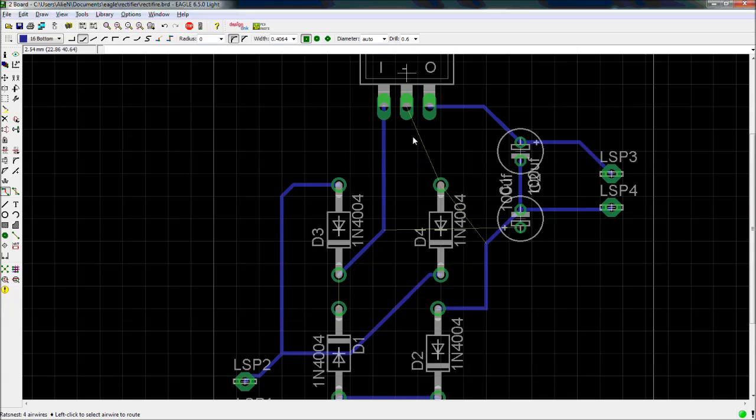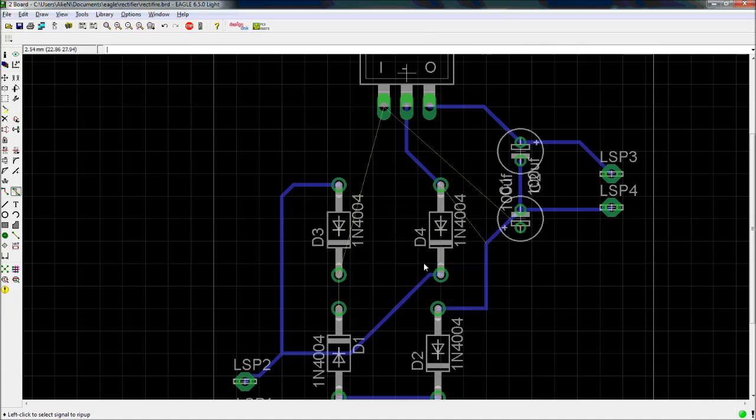Now you can see this. I'm connecting another wire, but this wire got in a cross connection. Fine. So if I connect this to this one, yes, it will be in a cross connection over here. So this is not allowed because we are using single side, so wires shouldn't cross. Fine.